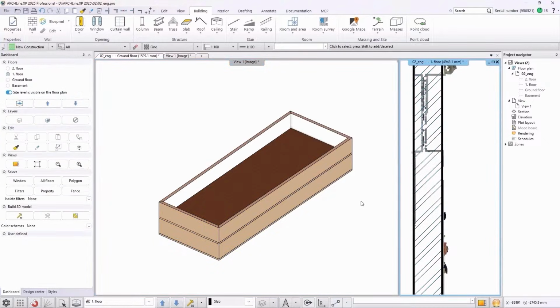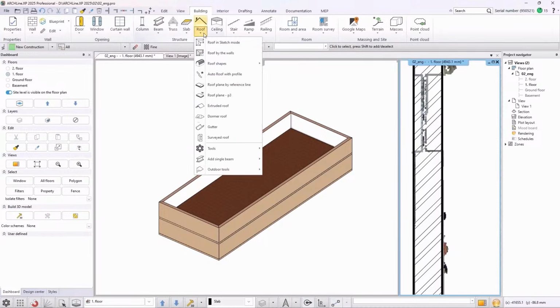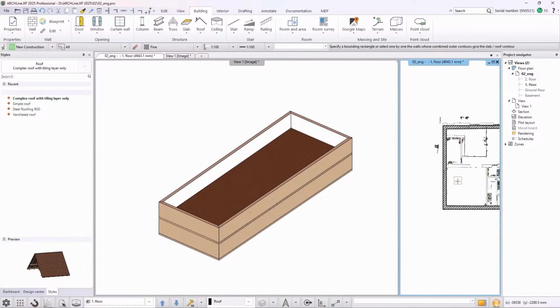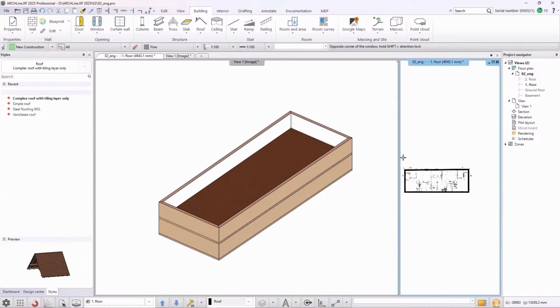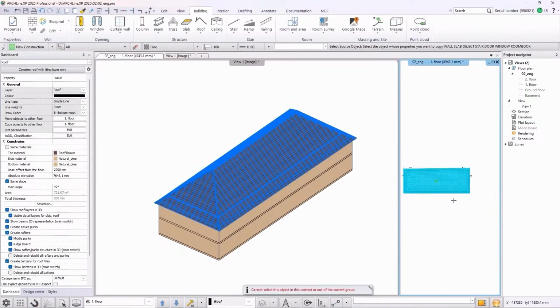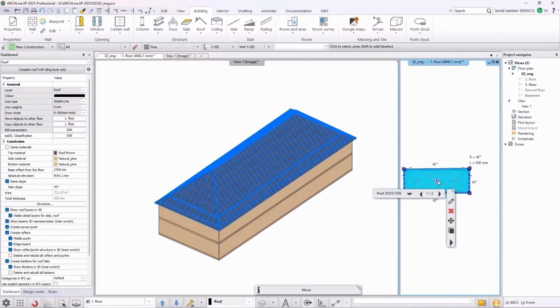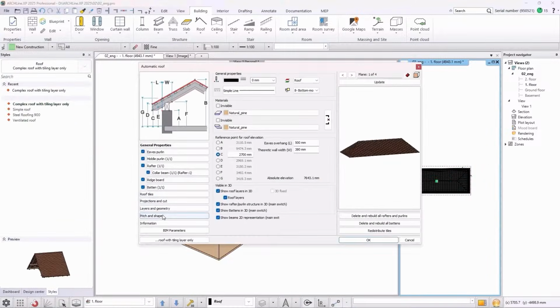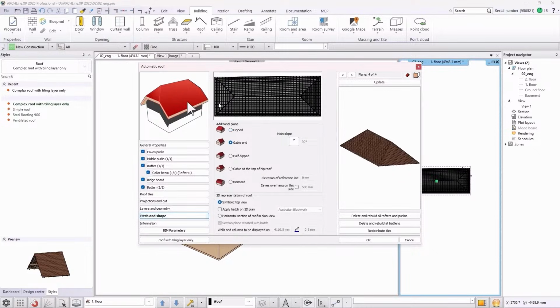Add the roof to the building. The roof is created with the default settings because we want to change its parameters after it was created. Enter its properties and create a gable end at the two shorter sides, then set the remaining two planes' angle to 13 degrees.